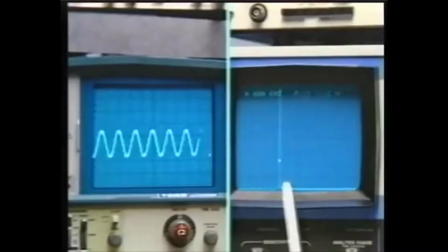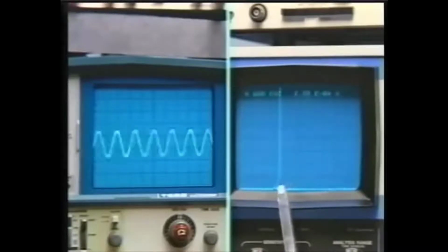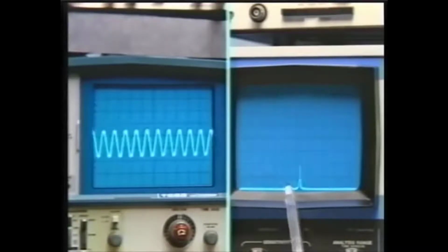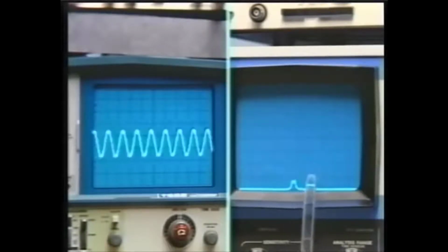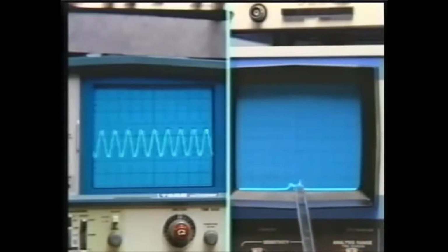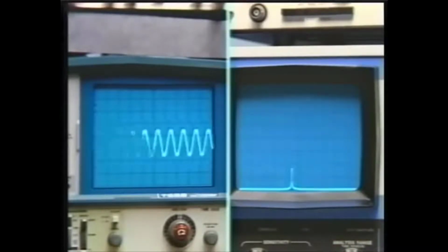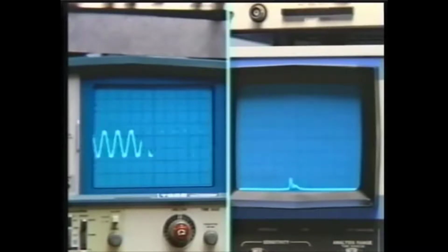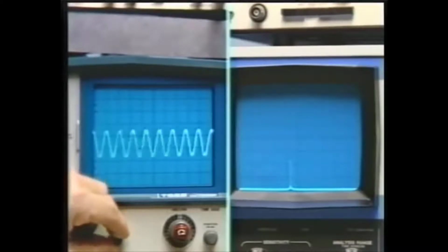Now, as Sandy varied the frequency, he did it slowly, and we saw the line move as a single line. Maybe now, Sandy, you could vary the frequency more rapidly, and what we'll get is a spreading as we go. Let me turn the cursor off, and what we'll see is a spreading of the line, so that the frequency content is richer, and the analysis of this is considerably more complicated. It corresponds to frequency modulation, where Sandy is now the modulating signal. We won't really be going into issues of frequency modulation in any more detail in this demonstration.